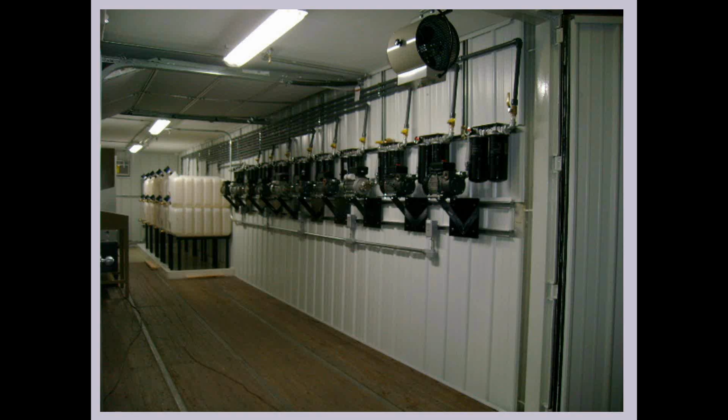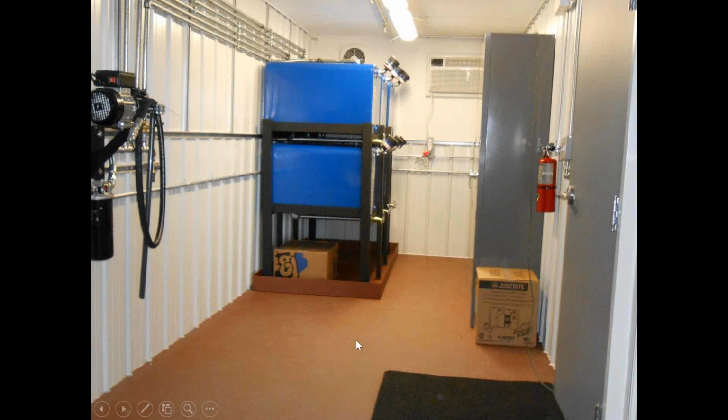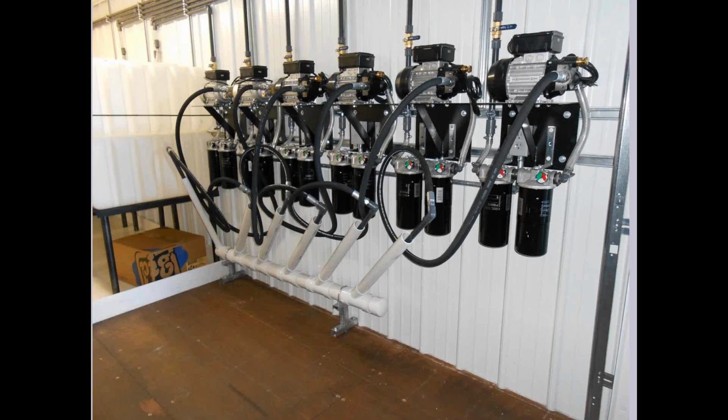So now when the maintenance person comes in to get his lubricant, all he has to do is go get a perfectly clean lube out of these storage containers, air-conditioned, heated. Here's one of our customers, it's got a steel floor, it's got spill control. They use steel tanks, which I don't recommend, but if they're stored in an ambient condition where they won't rust inside, they're fine. So here we've got an air conditioner, heater, steel floor, steel piping. Again, we basically build these for what the customer wants.